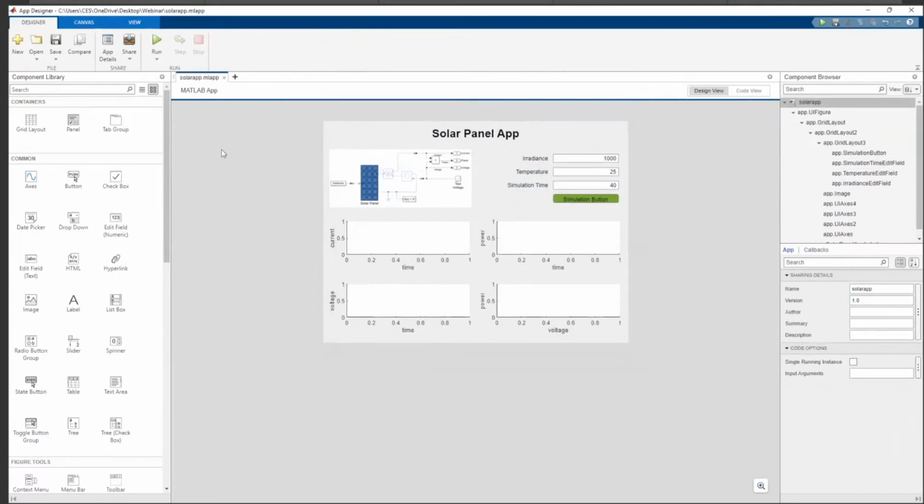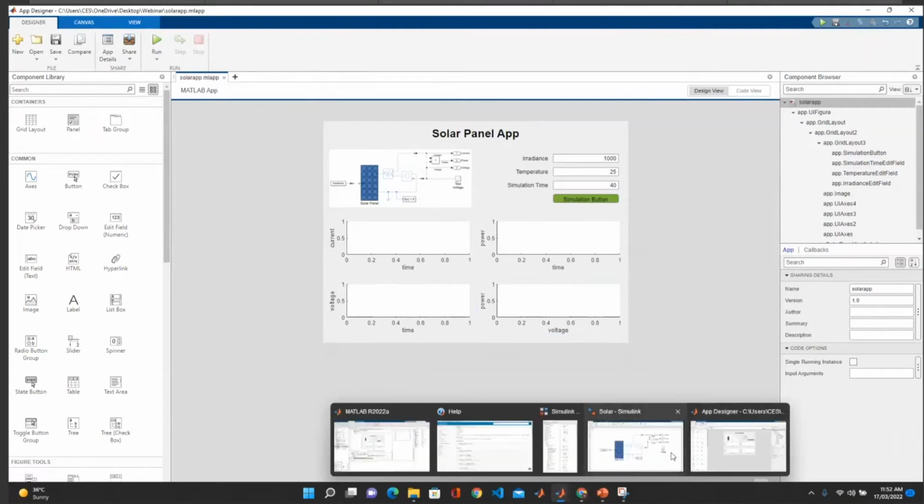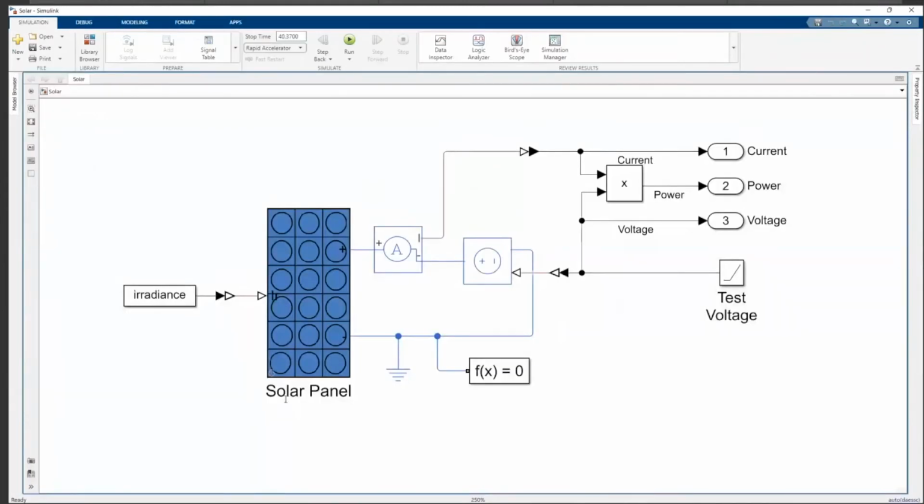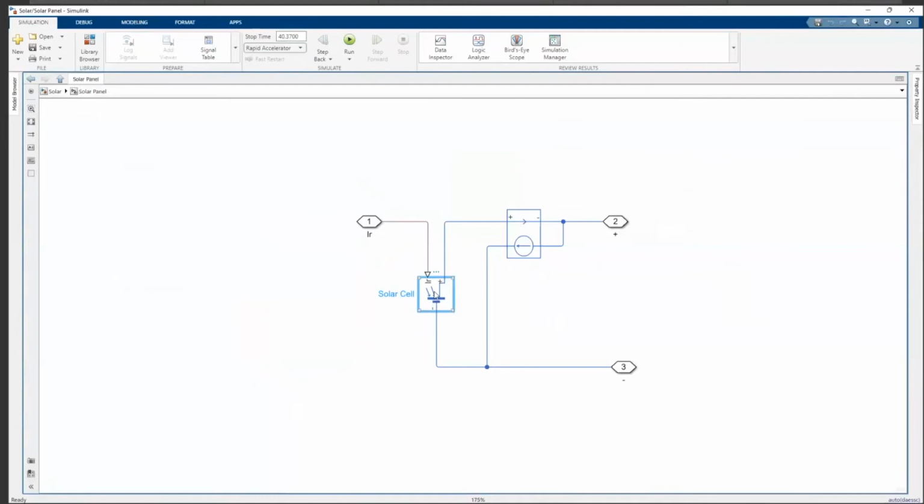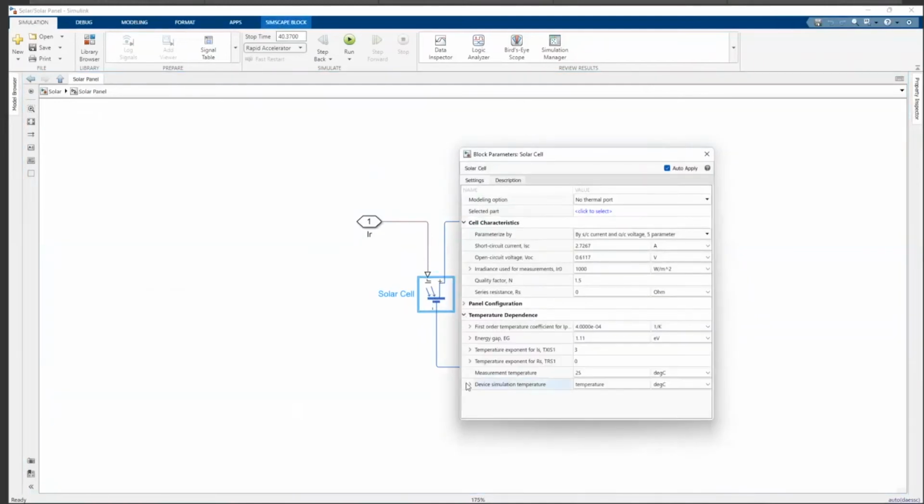This is working. Next, when we go to the model, there is one thing we have to change. In the model for the Simscape blocks, we have runtime and compile time. By default, all the Simulink parameters are compile time, which means you cannot change the value of the compile time parameters in the model or in the generated code without recompiling the model.